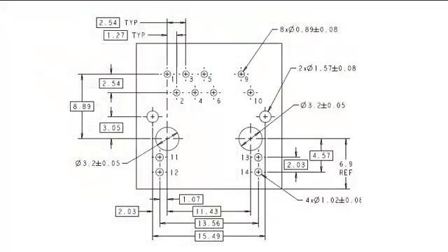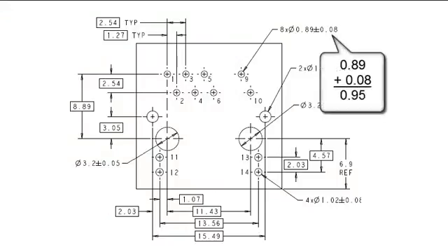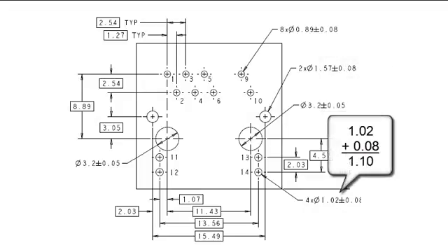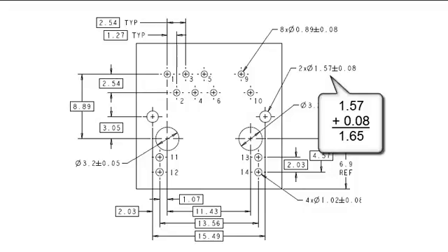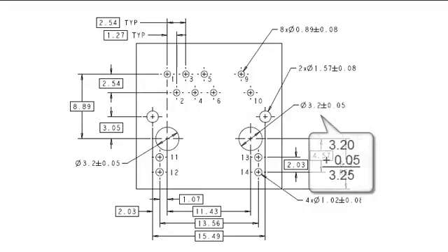The data sheet gives us the manufacturer's recommended hole sizes. For signal pins, it's 0.95 millimeters. For the LEDs, it's 1.1. For the shell ground, 1.65. And for the non-plated mounting holes, 3.25.